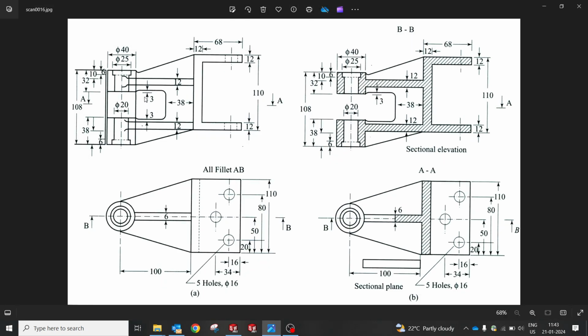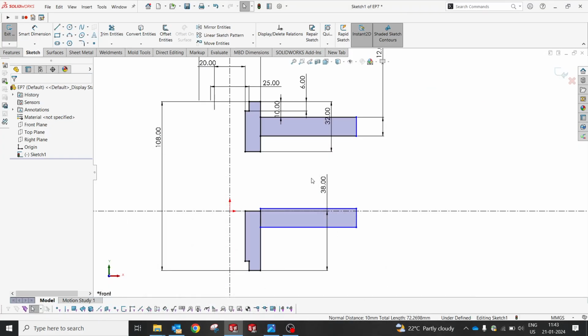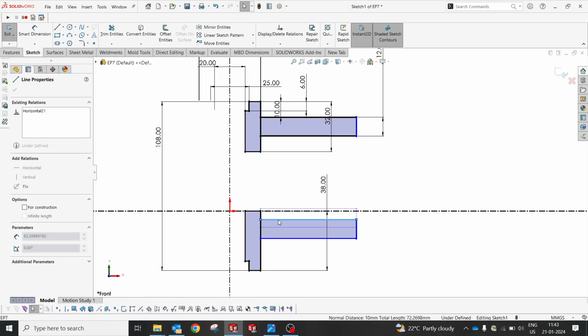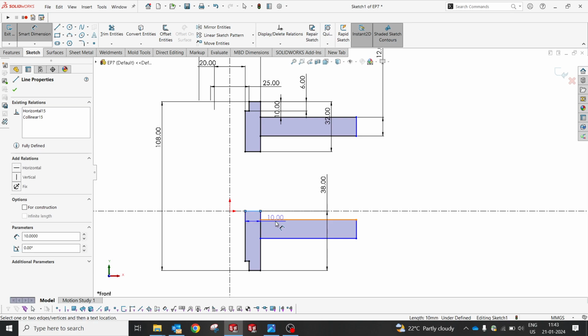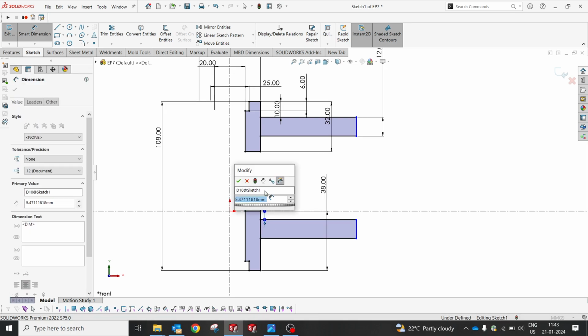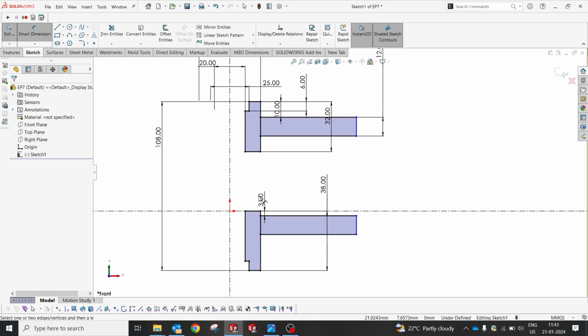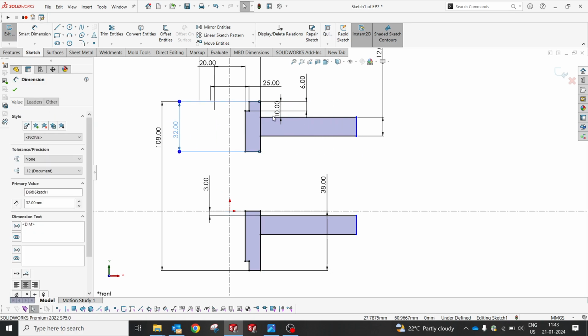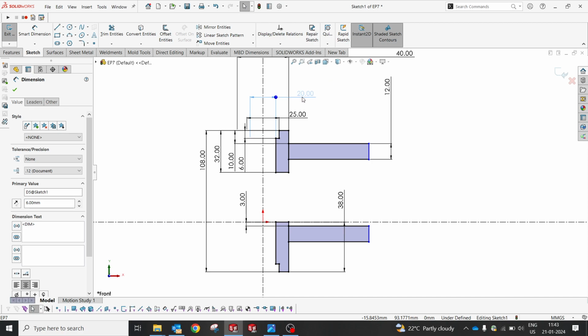Okay, that is for this rib. Okay, 3, not for this. Now it's cool. So from here, both sides are 3 mm, so try to maintain the same. We will try to move this and maintain the 3 mm. Yes, perfect. So almost all the dimensions are covered, and we'll try to maintain all of this the same. Try to align the dimensions so it won't be meshy later.